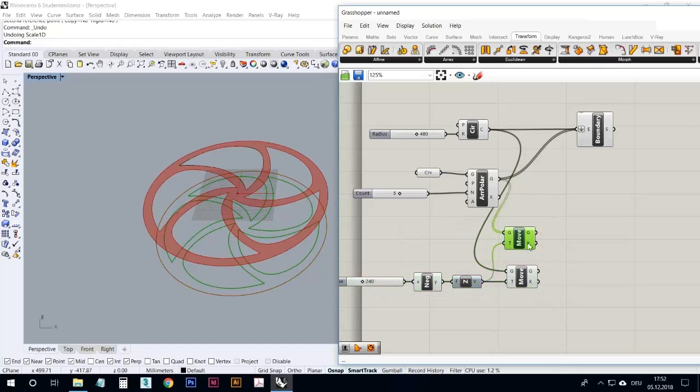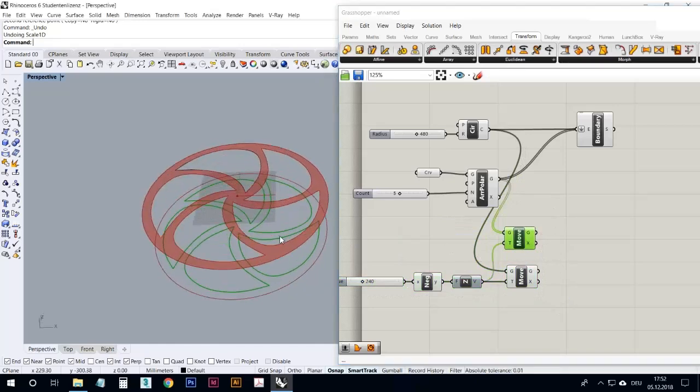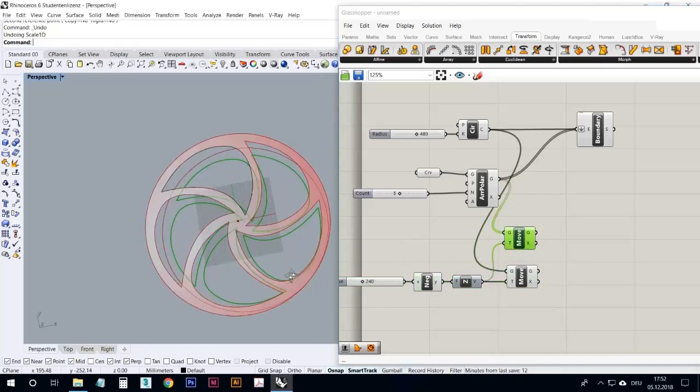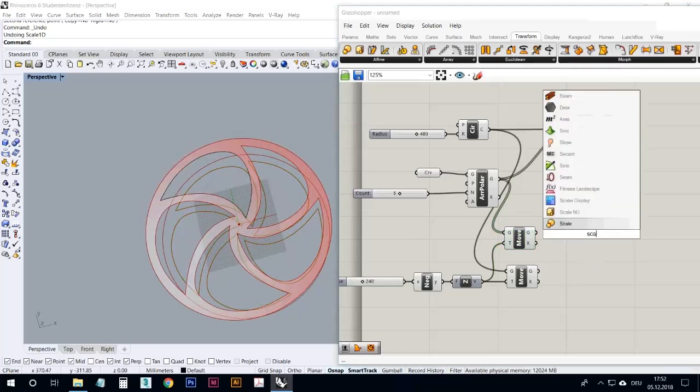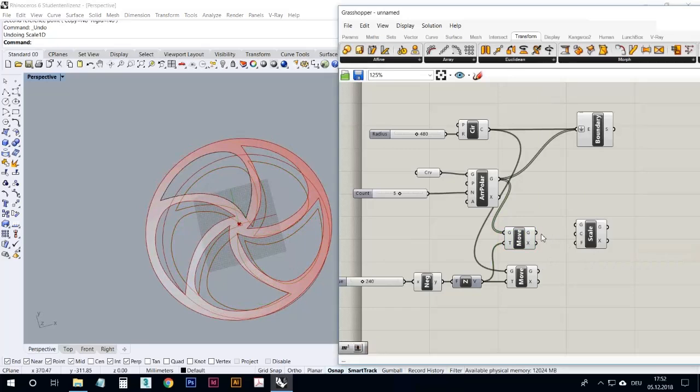So now I have another floor, but I wanted to diminish these, right? So one thing one can do, depending on the shape you have, you can also scale them. So if you go to scale, look at that first. We need the geometry to be scaled. We need a center of scaling and factor, which is 0.5 on default. Just see what happens here.